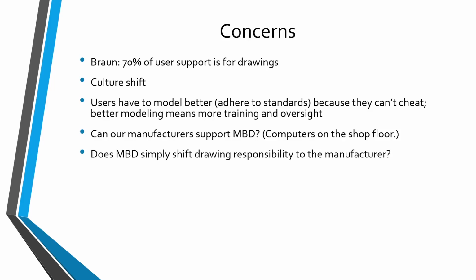Okay, so another concern: let's say that your manufacturer can't support model-based definition. One thing I've seen happen is that you provide the models to the manufacturer and they just turn right around and create a drawing so that they can manufacture to it. So in other words, you're not really saving anything.